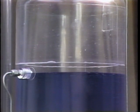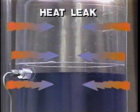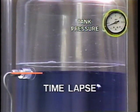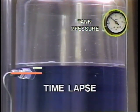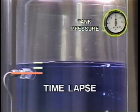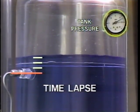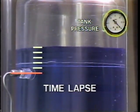Cryogenic customer station tanks are insulated, just like a thermos bottle, to keep the heat of the air from boiling away the product. But the insulation is not perfect. Some heat does manage to reach the liquid. As the heat enters the tank, the liquid warms and its vapor pressure slowly begins to build. At the same time, there is a decrease in liquid density, or its weight per gallon, and a corresponding increase in liquid volume. Yes, the liquid physically grows. That's why it's extremely important to stop filling the instant liquid comes out of the full trycock.